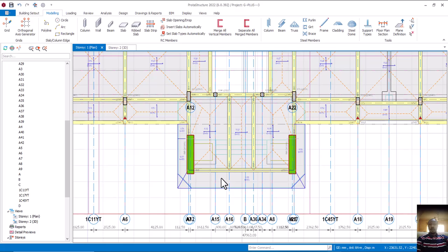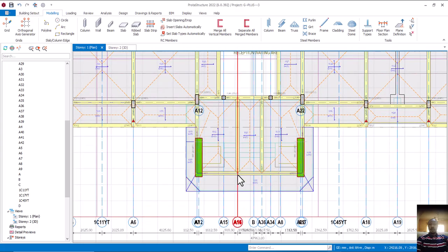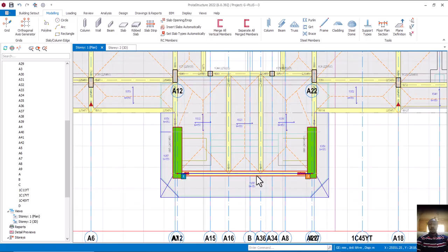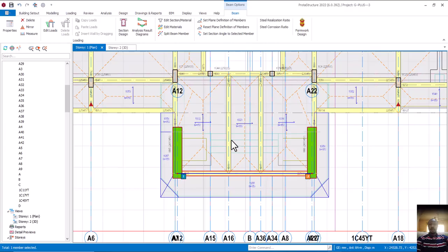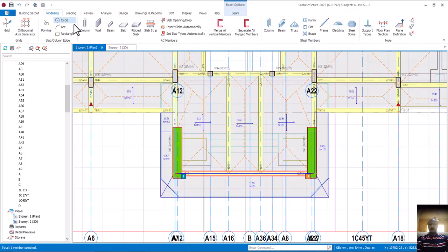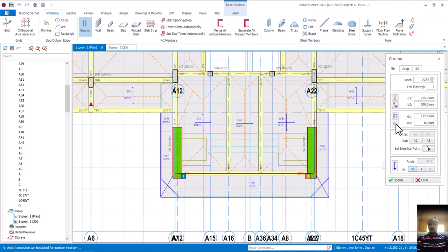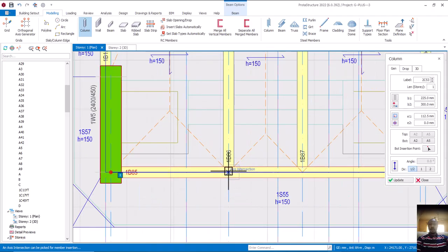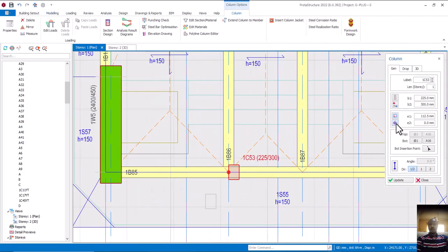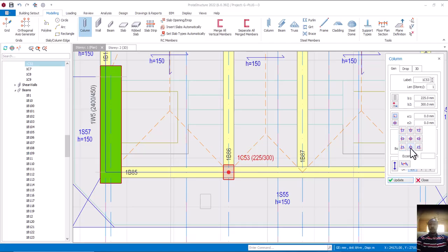Now don't forget, in this case we are going to be having our beam along this part. Is that okay? But before then, let me delete this. Okay, let me leave it. Let me take my beam property under modeling and let me keep column, rather not beam, column. I'll come here now. I'm using a 300. Let me see the shape. Okay, it's okay. So come here now, click on this. Let me say eccentricity. Okay, update, and then let me say the edge at the edge here, update. Okay, no, let me see, let me take it back to eccentricity, update.